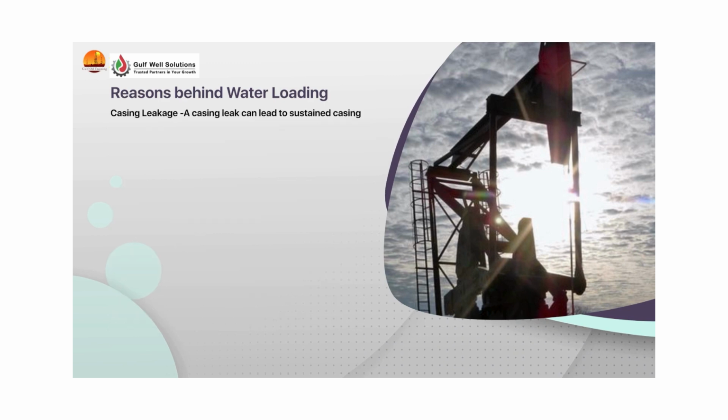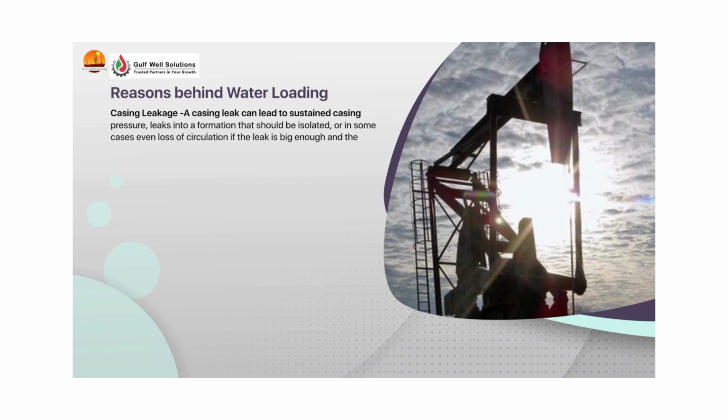Casing leakage: a casing leak can lead to sustained casing pressure, leaks into a formation that should be isolated, or in some cases even loss of circulation if the leak is big enough and the formation cannot hold the hydrostatic pressure.